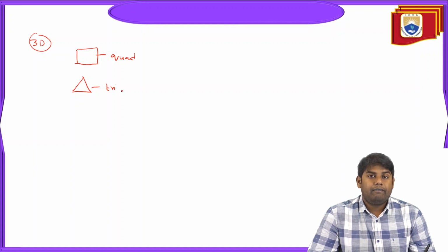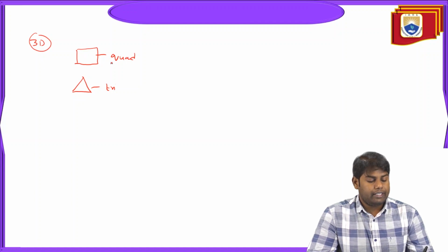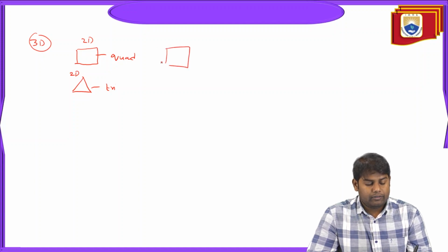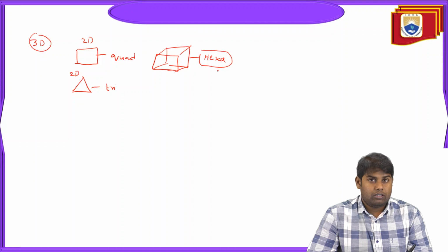Okay, and when it is projected to 3D, so this is the 2D cell, the 2D smallest cell. This one will appear for the structured mesh and this one will appear for the unstructured mesh. Okay, so if you take the structured mesh, the 3D entity, what do we call this one? Hexahedra. So we call it hexahedral cells.